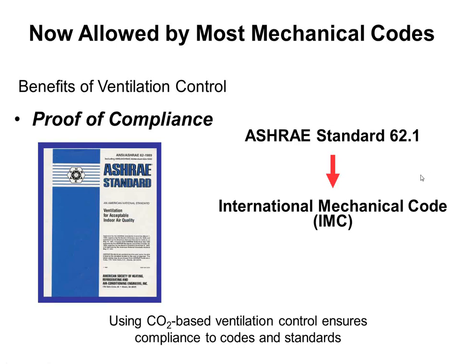All right, so as we were saying where we left off from last week, ASHRAE 62.1 is the de facto ventilation standard for the country. That feeds into the International Mechanical Code. For the most part, they cut and paste the language in there. And then in most cases, that also feeds into the local mechanical and ventilation codes.